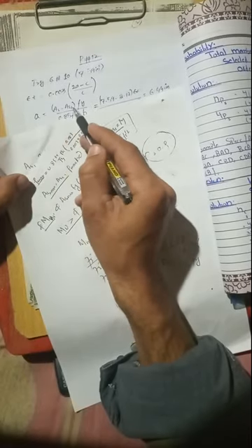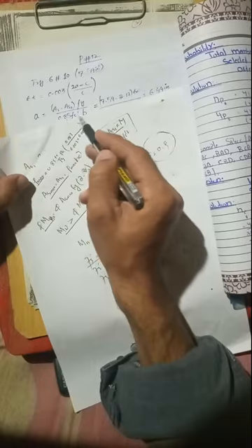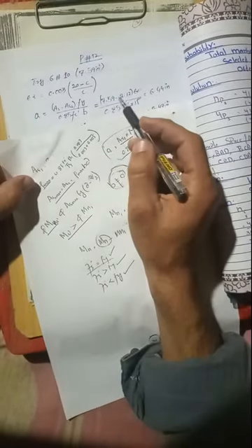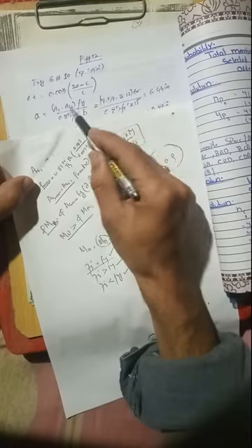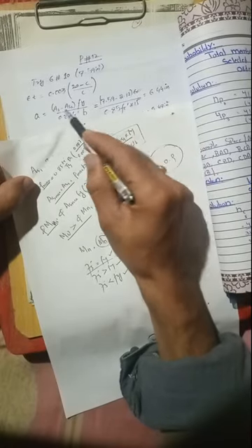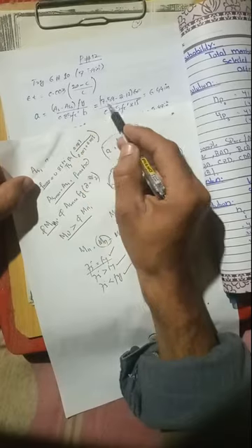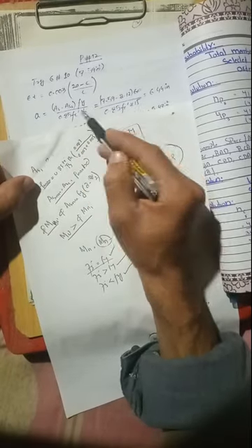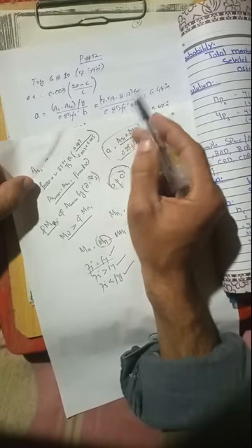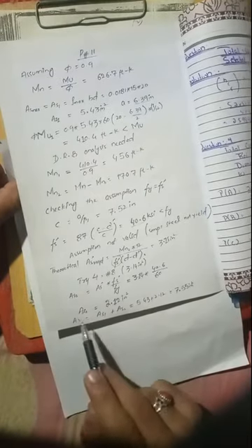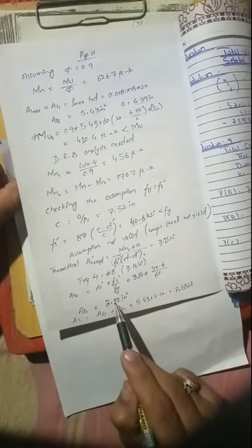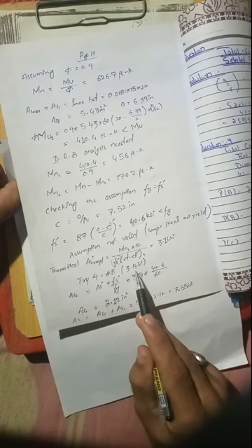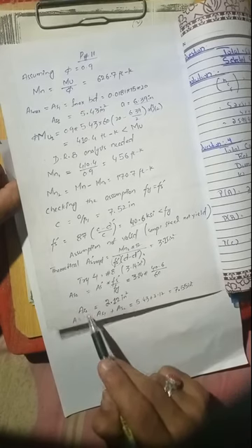This is As minus As2 into fy into 0.8, as usually we do in the 10.9 example, right? So As is already given, As2 is calculated 2.12. Remember, we are using the actual values. 7.59 is the actual value, As2 2.12 is the calculated value, we already calculated it. So this is important. Here it is 2.12, right? Not 3.14, right? This value is 2.12. This is very important.